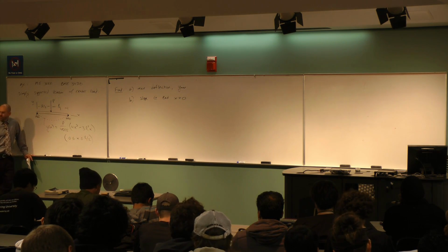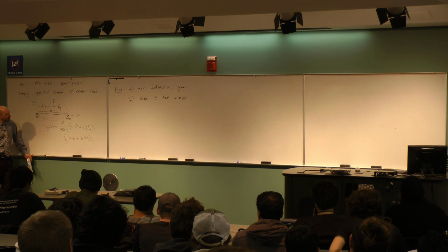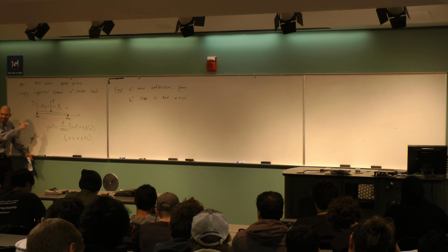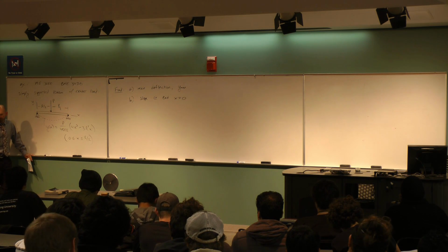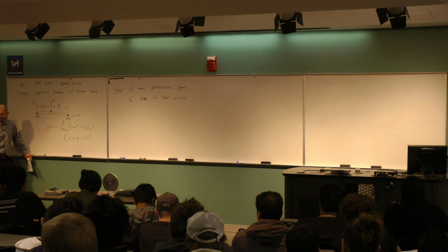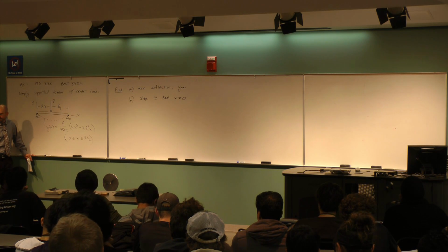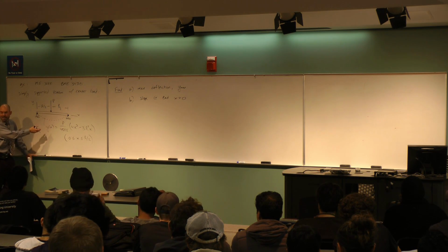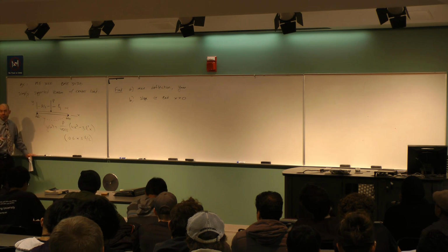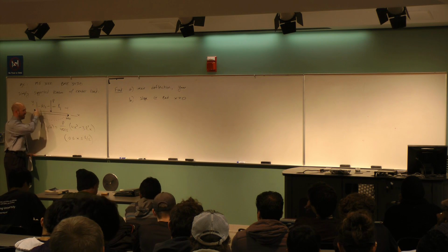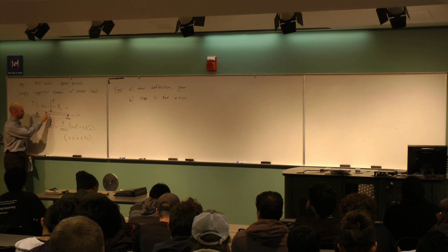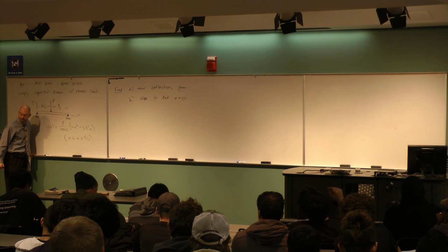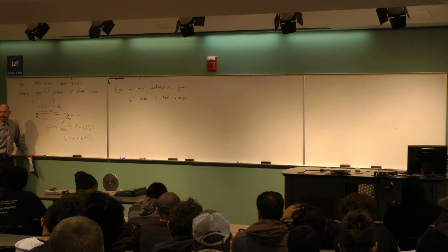All right, so a couple ways to think about this problem. If I want to know the maximum deflection for this problem right here, do I need to use calculus to do it? Any thoughts on that? So you're saying by inspection, I can see that the max is going to be in the middle. By the way, that's a symmetry argument for this problem. This whole problem is symmetric. It's a curve, so the only way that works is if this thing here is symmetric about the middle. Great. So I could just plug in L over 2.